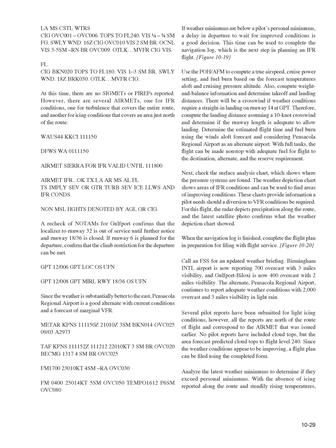Figure 1019, use the POH/AFM to compute a true airspeed, cruise power setting, and fuel burn based on the forecast temperatures aloft and cruising pressure altitude. Also, compute weight and balance information and determine takeoff and landing distances.